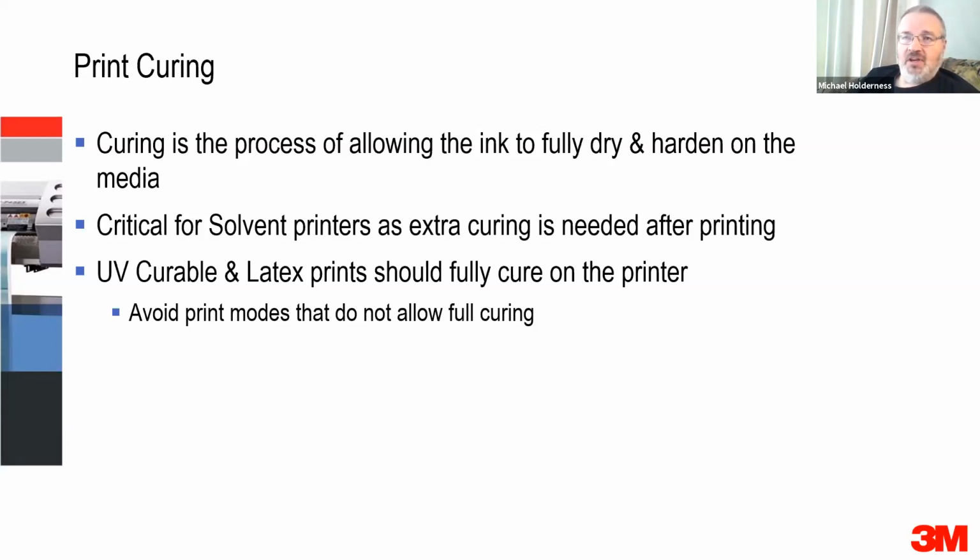Now, a latex print. What you can get with latex printers is a print that appears to be cured straight out of the printer. You'll print it and think, hey, wow, this looks fabulous. You'll put it on a table and about 10 minutes later, it gets tacky again. Essentially what's happened is you've cured the surface and there's still some moisture inside that's coming back up to the surface. Unfortunately, sorry guys, that's game over. Throw it away, it's never going to cure properly.